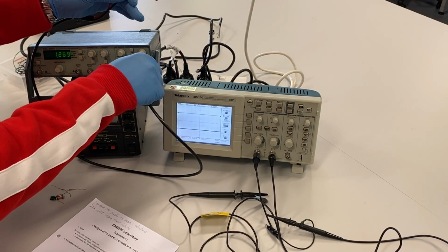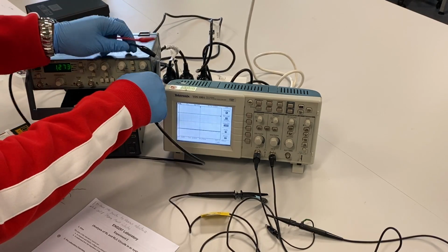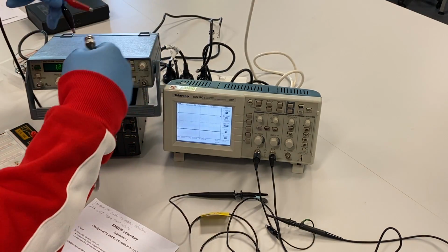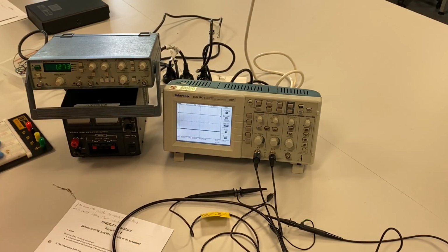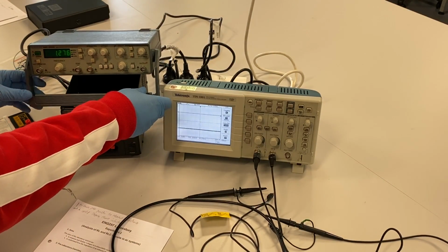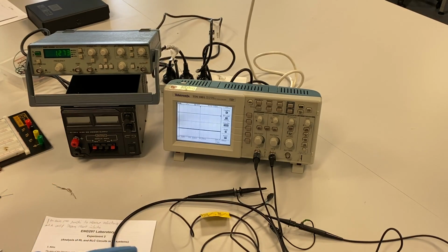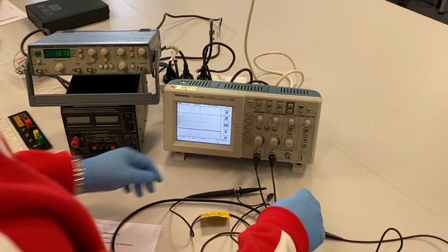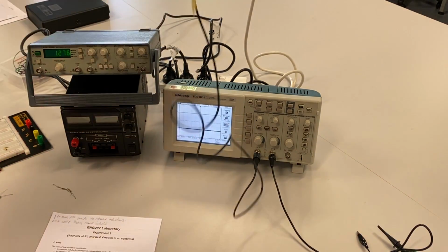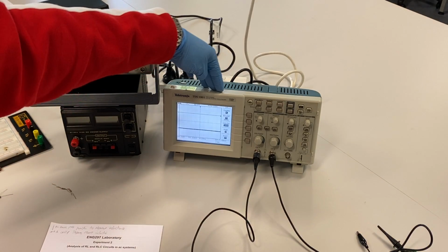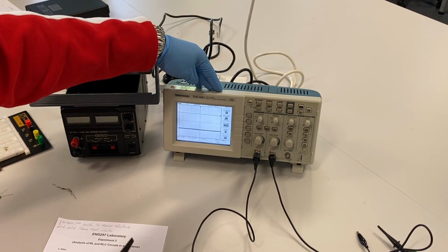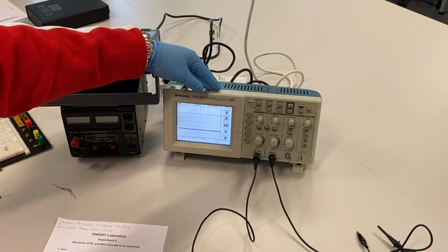But before I put it here, what we need to check is if these cables are working, because sometimes the cables will be broken. If you work with a cable that's not working, at the end of the experiment our signal will not come out correctly, and we will face problems, maybe 1 hour, 2 hours, trying to fix the circuit diagram, but maybe it's not the circuit, it's actually the cables. So we need to check. We use an oscilloscope to check them. What they should do is give us a square wave if they are working.